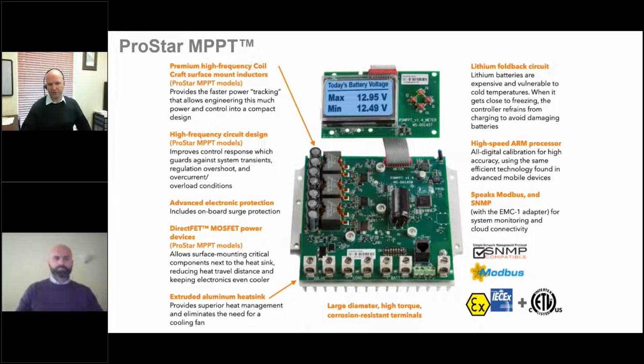Looking inside the controller, we often like to talk about the design inside the chassis, because the circuit board is just as important as the case in providing long life. You can see we have a unique three-phase design there, not three-phase AC, but three individual circuit phases for the controller, and that allows it to have much better efficiency overall and run cool. We have the ability to support Modbus again, of course, in this product, and some of our more unique features, such as our use of direct FETs and high-speed ARM processing for all of our products.